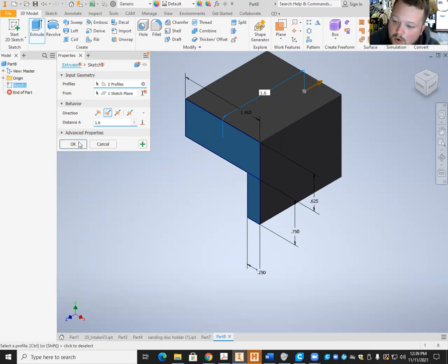Not really. One thing you will notice at times, sometimes it'll be really tough to select the geometry you're looking to extrude. If that's the case, it's honestly because you have a bad loop, which means that the 2D sketch you did didn't go so well. Maybe it didn't close up. Maybe it's kind of a line, not per se a loop. So there's a lot of functionality with that. In the 2D sketch environment, there's a right-click close loop tool.